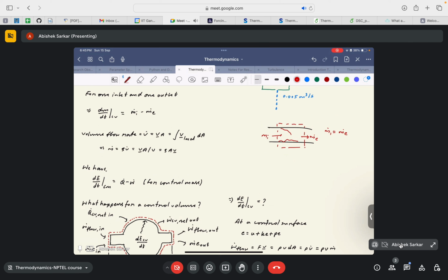Okay, so again, this is the formula for finding the mass flow rate. It is given by rho A V, where V is the velocity of the flow, A is the area of cross section through which the flow is occurring, and rho is the density of the fluid. Okay, this is quite simple, and I'm just reading it out so that you're not confused with the terminology. So don't get confused with V for volume. So here it is specifically given as a vector, that will imply that this is the velocity. Okay, so capital V without any vector sign is volume,